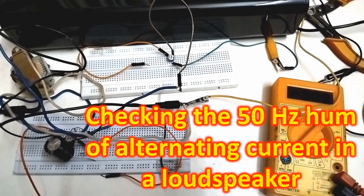Simple way to experience the 50 Hz of the alternating current supply voltage is to connect it with a step-down transformer to a loudspeaker. A potentiometer can be used to reduce the current going through the speaker to prevent damage to it. The hum which you are hearing is the hum of the power supply which has been connected to the speaker using a 50 kilo ohms Cermet preset potentiometer, that is to show the AC hum in direct connection from the transformer to the speaker using a potentiometer.